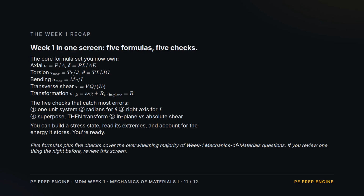The Week 1 recap on one screen. 5 formulas: axial stress and stretch, torsional shear and twist, bending stress, transverse shear, and the transformation to principal stresses and in-plane maximum shear. And 5 checks that catch most mistakes. 1 unit system, radians for the twist, the right axis for the inertia, superpose before you transform, and in-plane versus absolute shear. You can build a stress state, read its extremes, and account for the energy it stores.